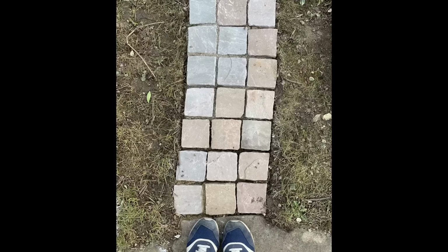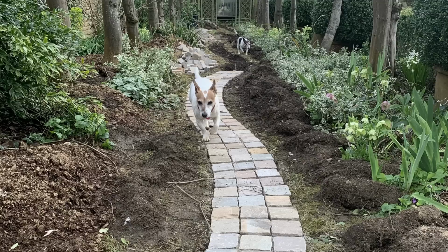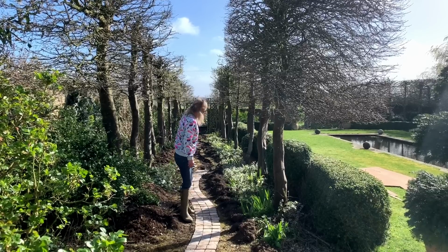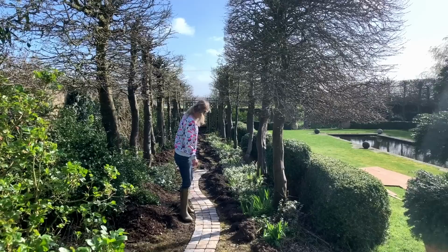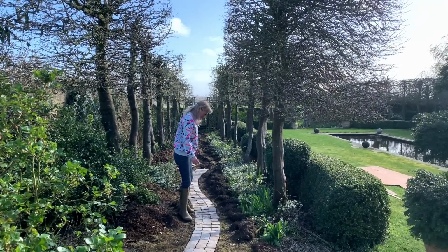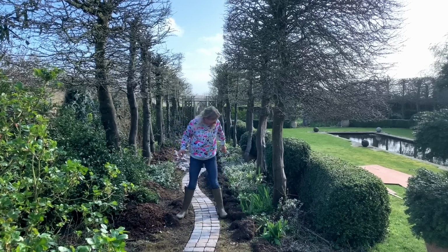So he's done the 3 bands of sets, and you can see they're picking up the wiggles of the curve, and it's a very regular serpentine. You can see I placed the sets along there for him, so as he works from right to left, he's got them there. And then when he's finished, so these are Indian Stone sets, they're Raj green, they're 100 by 100, let me show you one, and they're not sawn.